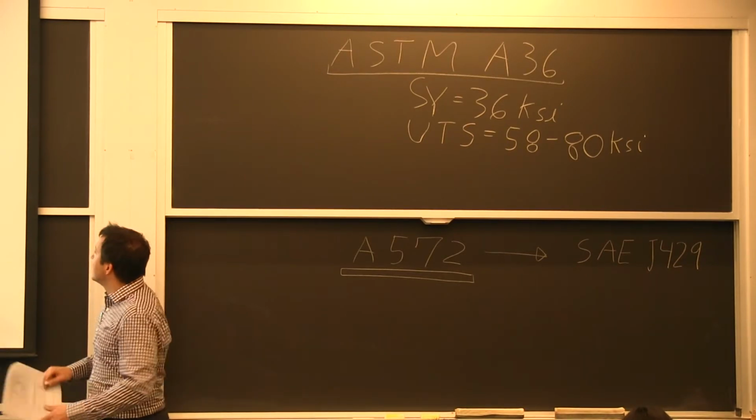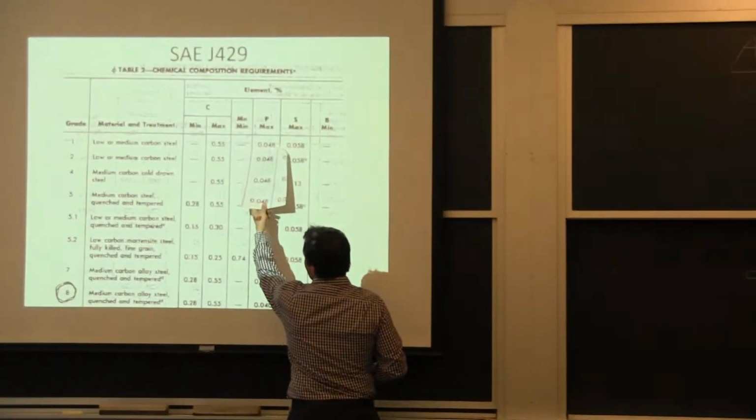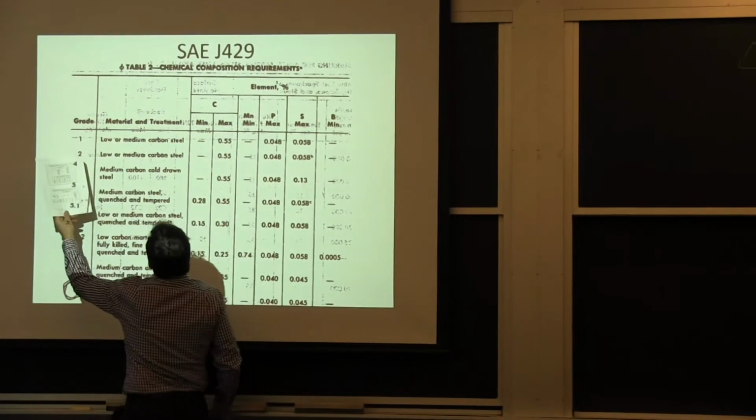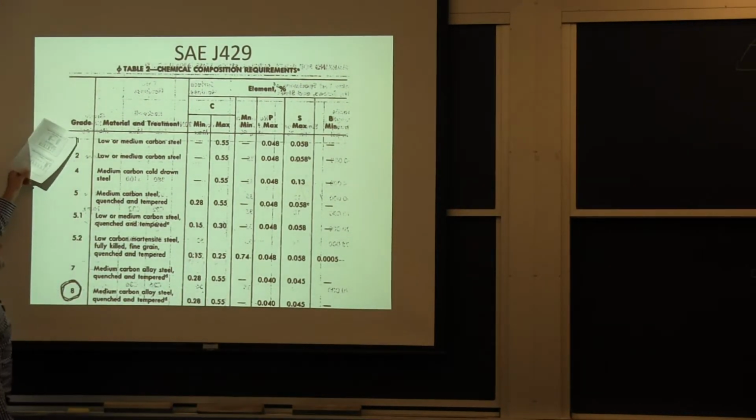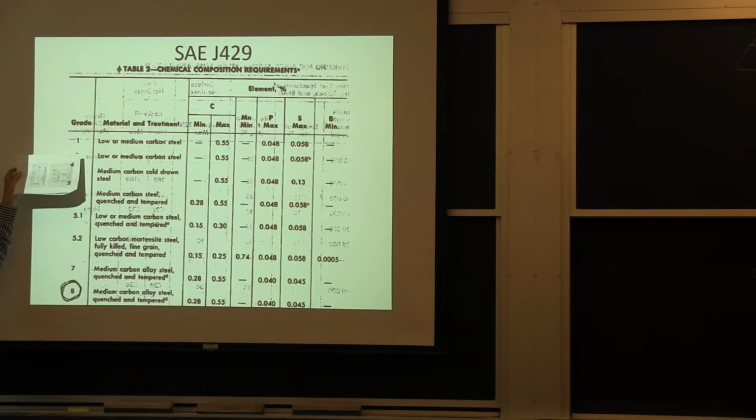If you look here at the chemical requirements for different grades, this is very, very basic bolts. You guys will not specify what you want if that's what you specify. You just get a utility bolt. And then grade 5 is fairly common. It does say quench and temper. Oh, that's interesting. And then grade 8 is very common if you're going to have repeated loads on a connection.